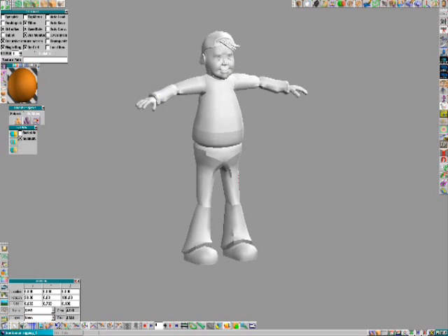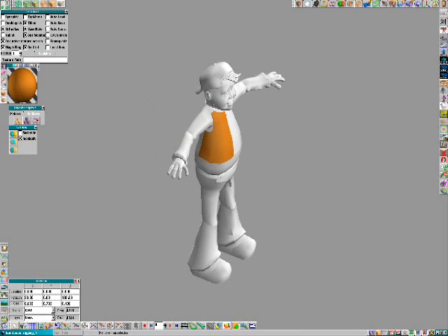If I start with my model, what I'm going to do is start by colour coding the sections. Different model applications will do this in a different way, but the basic tenet will be the same. I'm going to apply a colour to different sections of this model. So supposing I want all of this section to be the chest, I'm going to colour it all one colour. Okay, and I can continue round, and I need to make sure that, for example, at the collars, the chest will completely separate between the collar and the neck.